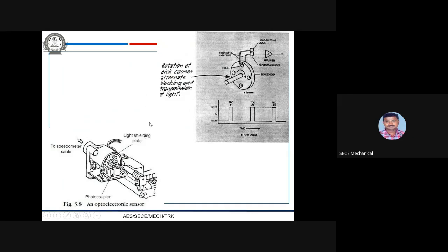The optical sensor converts light rays into electronic signals. Here the light rays pass through these holes, and the sensor measures the physical quantity of light and translates it into a form that is readable by an instrument. An optical sensor is generally part of a larger system that integrates a source of light, a measuring device, and the optical sensor. This is often connected to an electrical trigger, which reacts to a change in the signal within the light sensor. An optical sensor can measure the changes from one or several light beams.